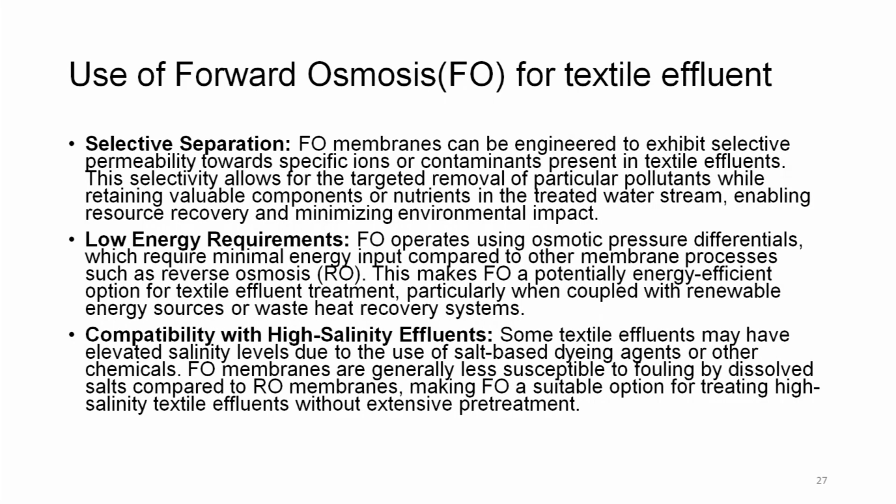FO membranes are generally less susceptible to fouling by dissolved salt compared to RO membranes, making FO a suitable option for treating high salinity textile effluents without extensive pre-treatment.